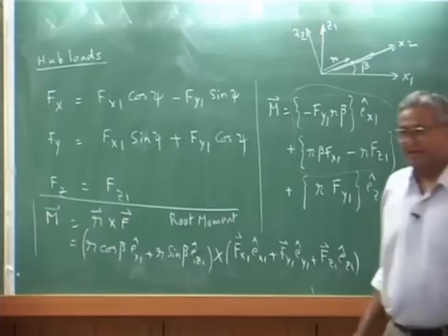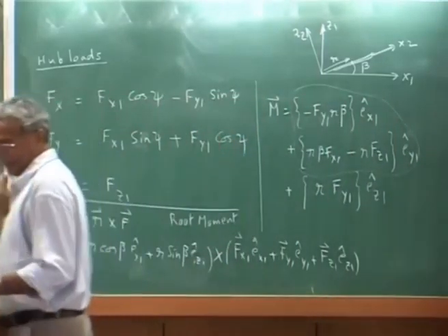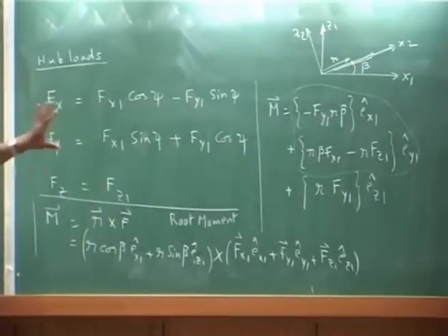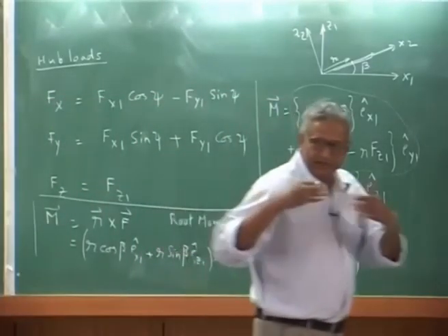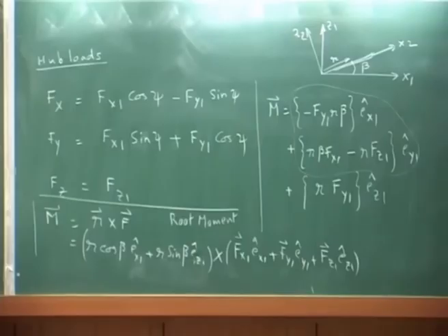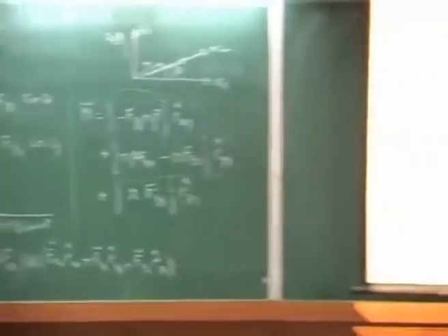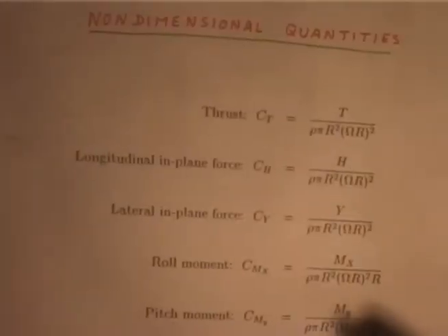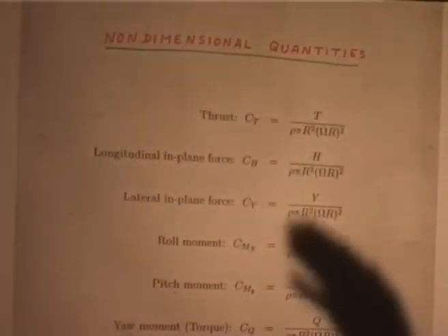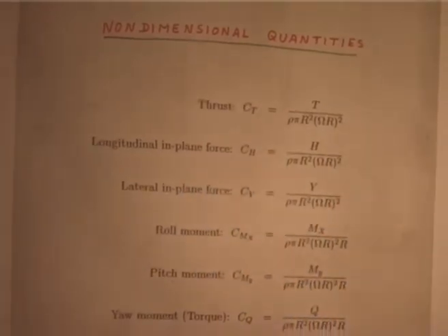Now, using this, I will represent all the quantities, because there is only algebra now. I do not want to again spend time on algebra. So, if you have any questions, you can ask me, because if this is clear, we got the sectional load and transferred to the hub, and then we also got the hub moment.